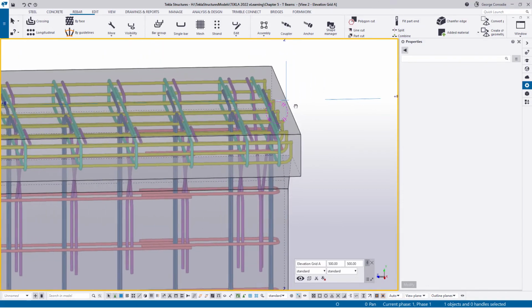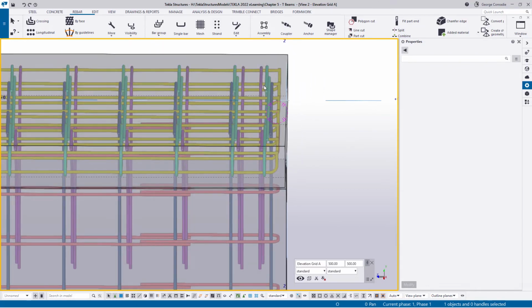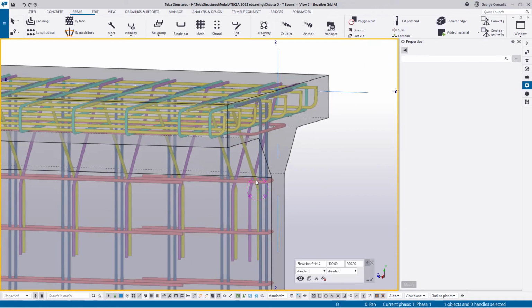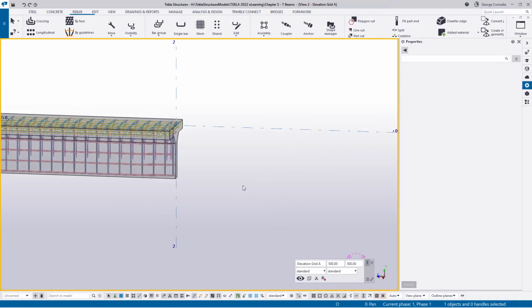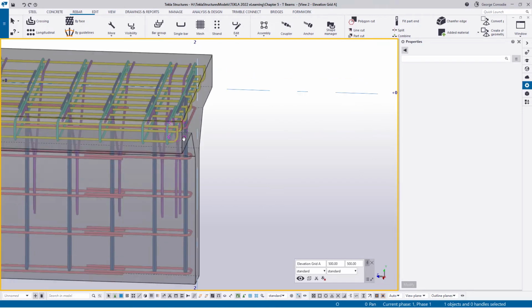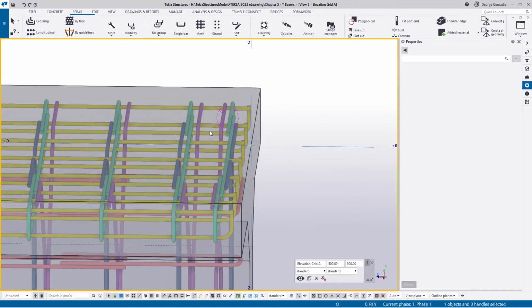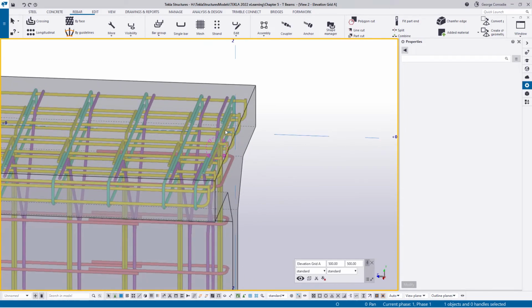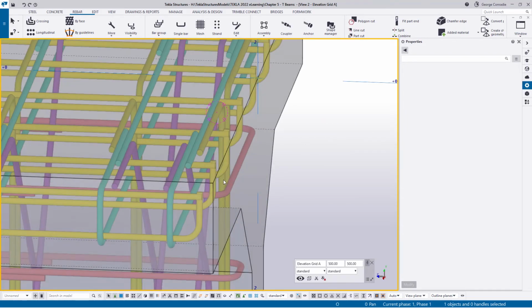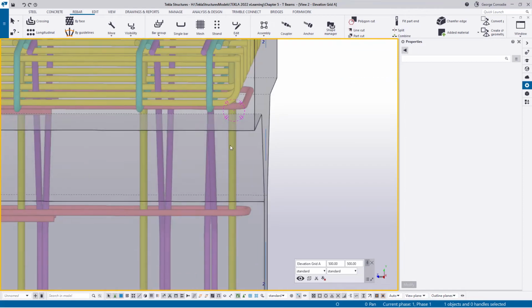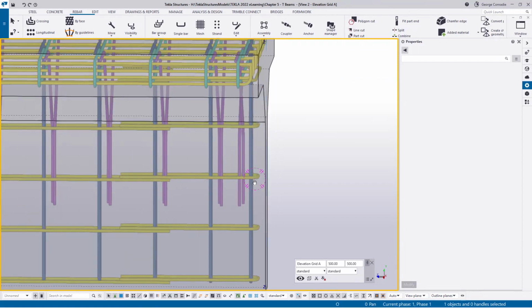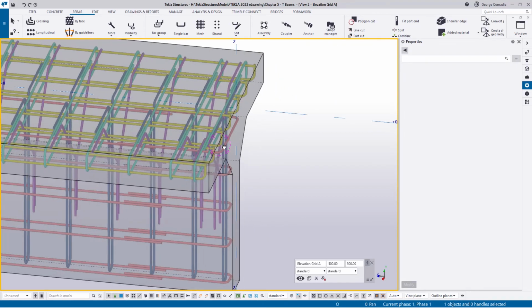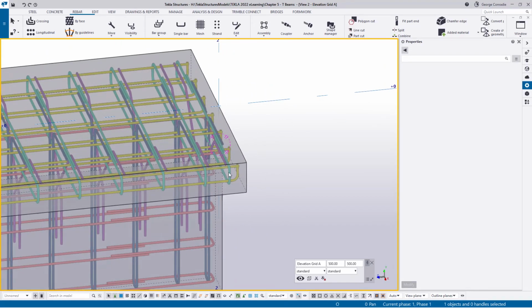So what we ended up doing is, when bars cross, like in this case, these two cross here, there's no way around it. You're going to have to just deal with that little void there, because no matter where you put it, even if you put it this side, they're never going to be smack bang on. Suppose you could put it at the end, but then you're going to have to see if it will fit in with your ligatures. And in this case, it probably would. But I prefer when they cross like that. It doesn't hurt anybody. So that sorts that out.